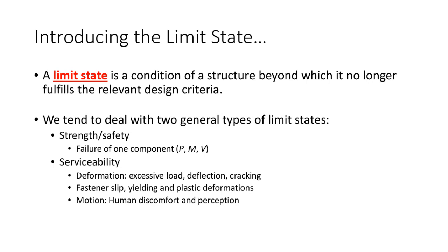What it means is, where did that L over 360 come from? If the beam deflects more than L over 360, you'll start to crack the plaster. Again, it's not a matter of safety, but if it deflects more than L over 360, it doesn't meet its day-to-day performance expectations.